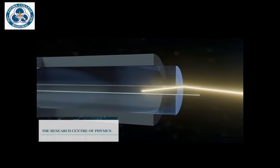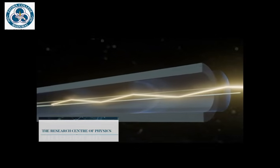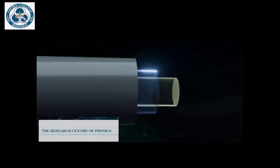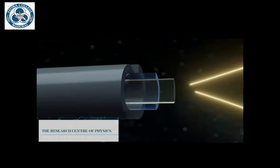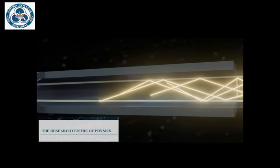Single mode fibers have a smaller core, usually around 9 micrometers in diameter. This allows light to travel in a single straight path with minimal signal loss, making them ideal for long distance transmission. Multimode fibers, on the other hand, have a larger core, usually around 50 to 60 micrometers in diameter.